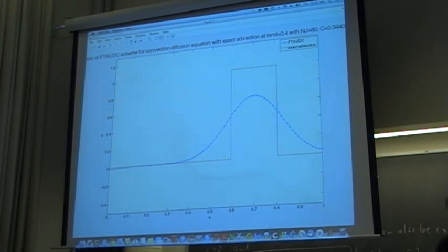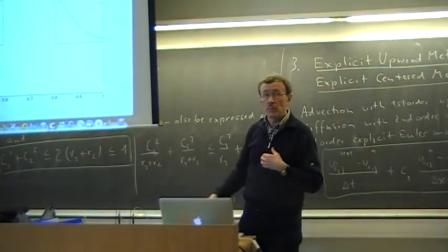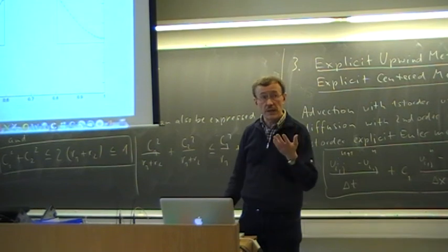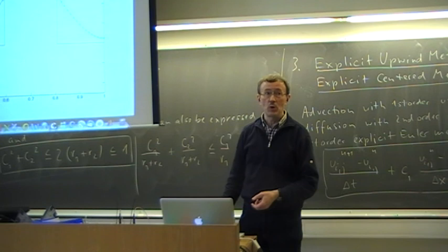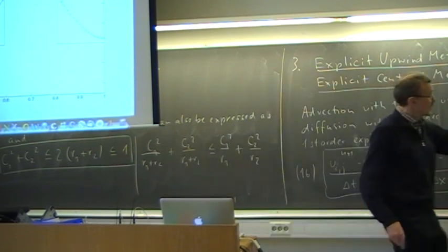Okay, so when we do the simulation for convection diffusion, we have to be careful about that, and that was the remark that we heard from Espen before, regarding the numerical viscosity. So here we have really quite some numerical viscosity. So therefore we need a fine grid here to get the accuracy good and to get the error low. But we have no problem with stability as long as this condition is satisfied.